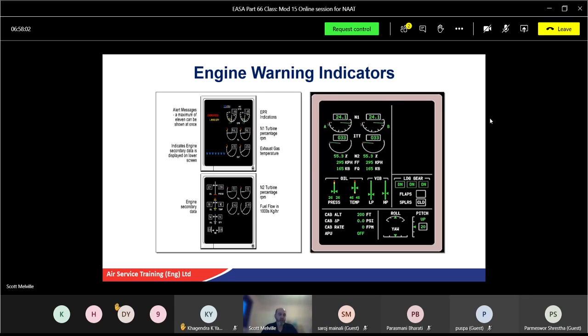So if it doesn't do it there, but it gets to 695 degrees, it's the last chance, really. Bleed valve closes. Yeah, bleed valve will be closed. Your over temp switch will be energized. What's the number for the air ground relay? R38. Yeah, good. Thank you.